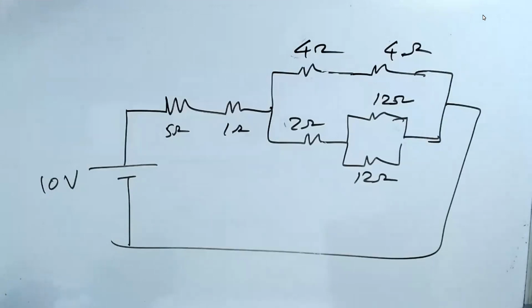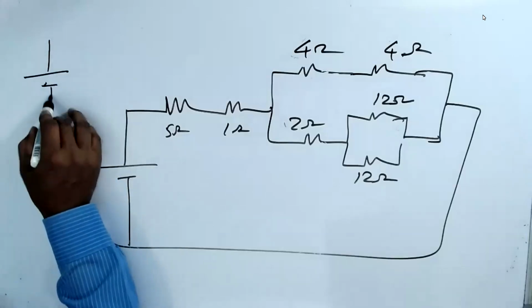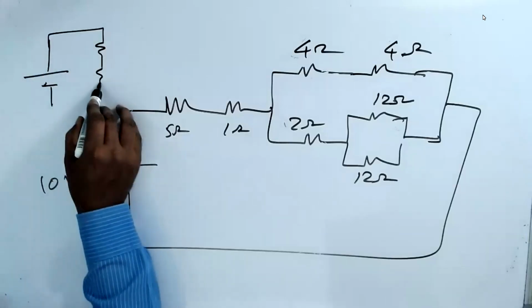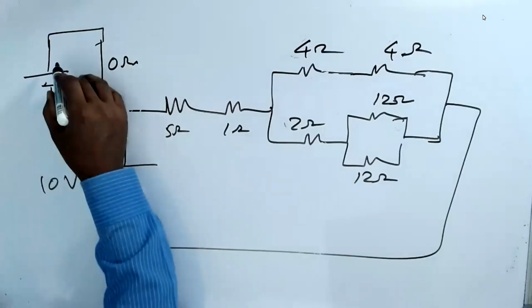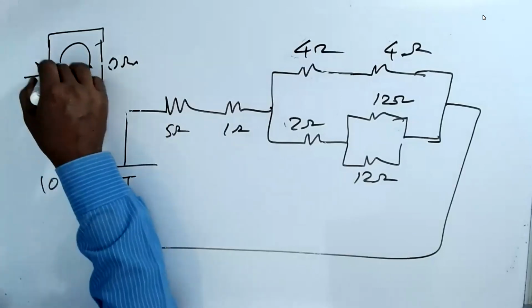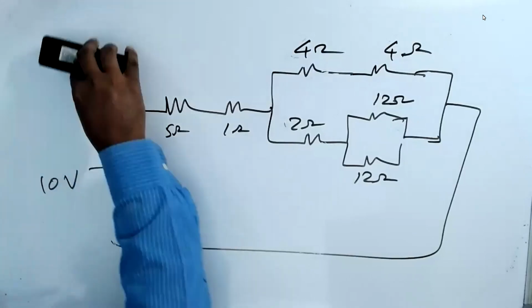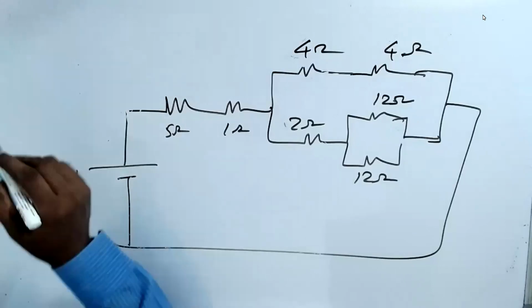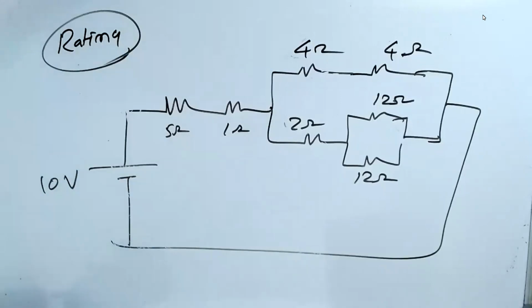The moment you see the circuits, I explained to you yesterday itself, both cannot be on. That is what I explained to you, that if both are on, it's 0 ohm. So the current is going to be very high. The battery will burn. This is called a short. You should never do that.